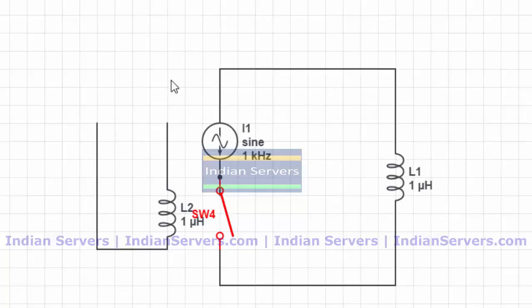From this circuit, we can conclude that by using a smaller voltage, we are going to operate a higher voltage, that is 230 volts. Here this coil can be activated by using some 5 or 12 volts. So here I am going to connect a voltage source. This voltage source is connected to the coil with the switch.